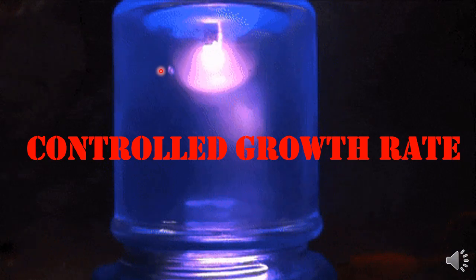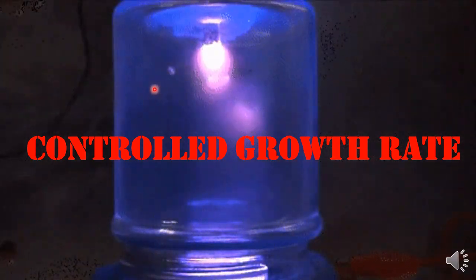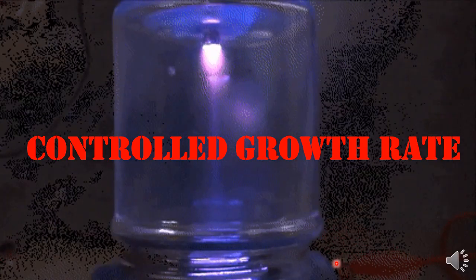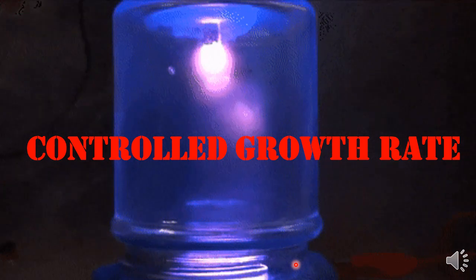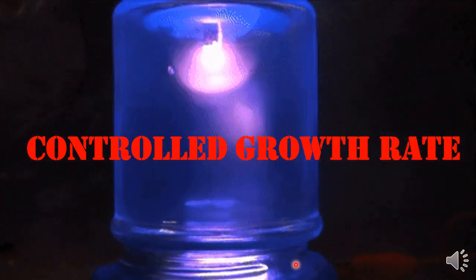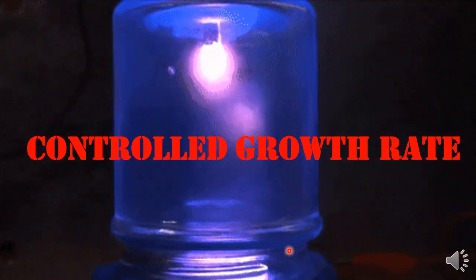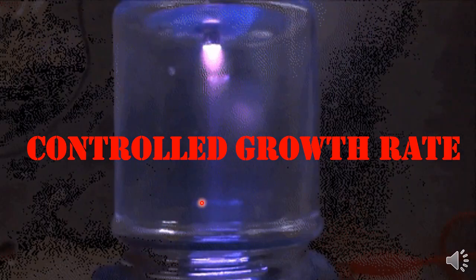Dear students, please note that MBE is a kind of complex process. The chamber of the MBE may contain different types of precursor. Let's say we want to deposit gallium arsenide and gallium aluminium arsenide on the substrate of MBE. Usually the substrate used in MBE is indium phosphide or gallium arsenide. Let's say we want to deposit different types of precursor like gallium arsenide and gallium aluminum arsenide.